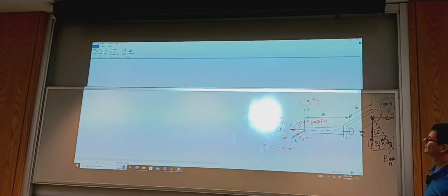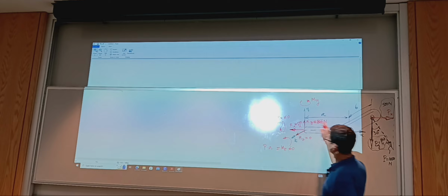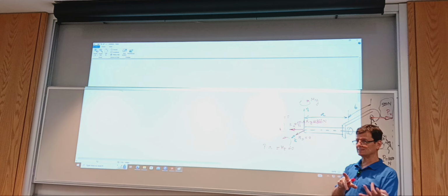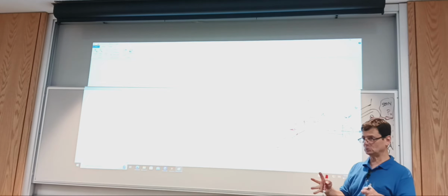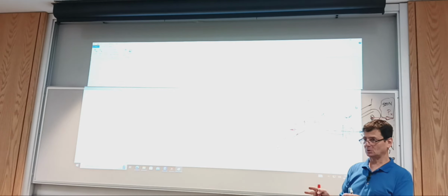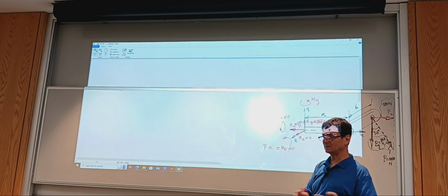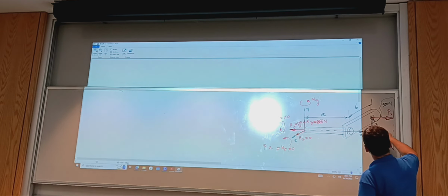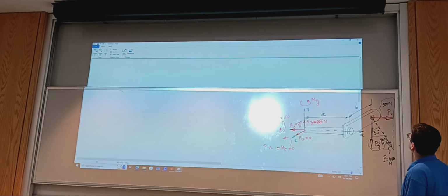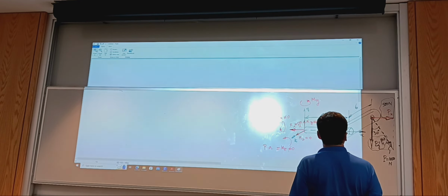Well, it was, but I changed it, so you either change the sign or you reorient the vector. I have a preference to reorient the vector and just put the magnitude on. But if from calculation you end up with a reaction that is negative, it means that the assumed orientation of that reaction force was not right. Not that it was wrong. Okay, so let's look at the moments now.